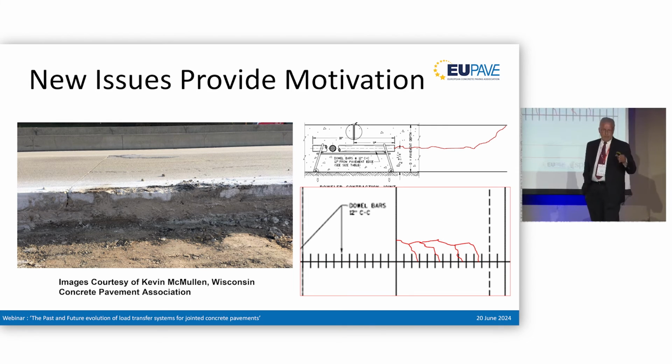We also have recently noted a type of pavement distress that perhaps suggests that with our accelerated paving systems, our dowel bar systems are too stiff for the young pavements, and we're seeing some delamination distresses across the dowel plane in the pavements. And this has driven at least one of our agencies to say, okay, we need to have smaller bars and more flexible bars. I think this type of thing will move people into tubular systems and FRP systems in the long term.